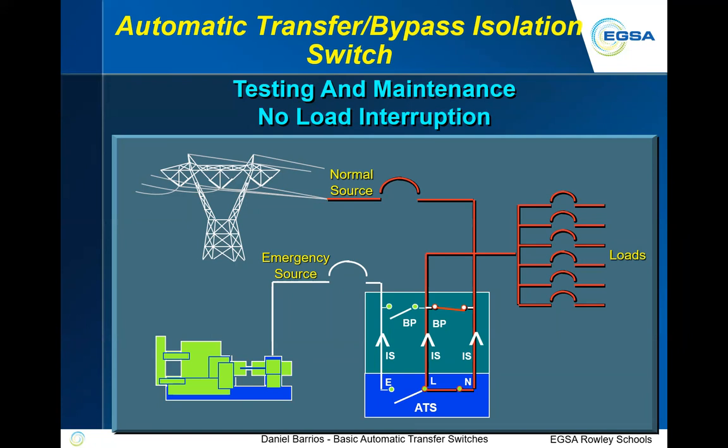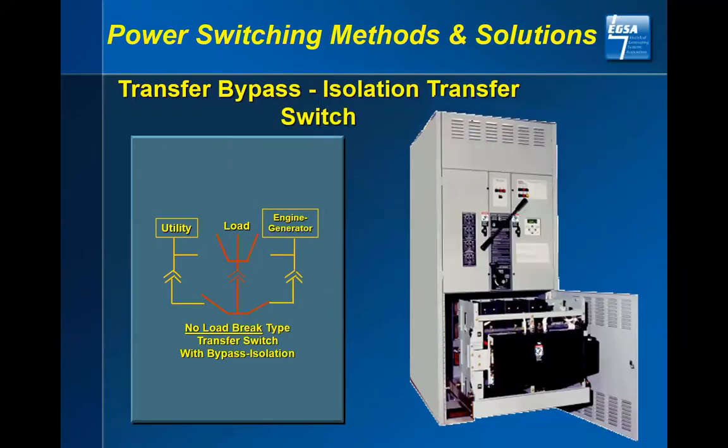Those upper contacts, that upper portion, is rated again for the identical criteria, amperage and withstand rating. This is once you're in there as a no load break type. That's the transfer switch. It's connected. It's removed. You have three positions. You have connected, where it's obviously in automatic use. You have a test position where you can rack the transfer switch into that portion and you can electrically transfer the switch back and forth to be sure all mechanisms are working correctly without disrupting anything downstream.